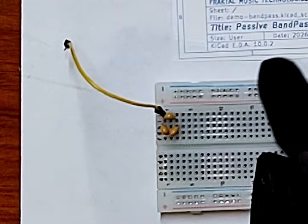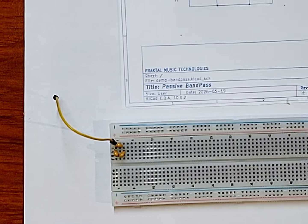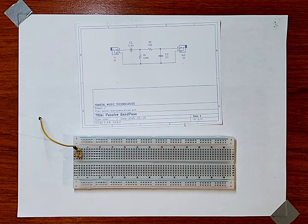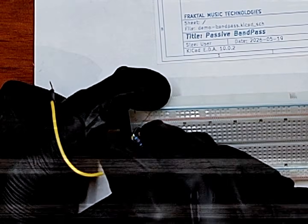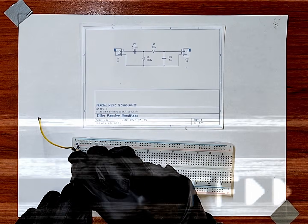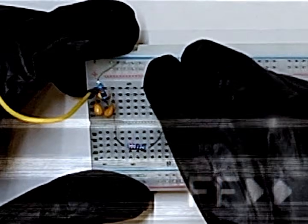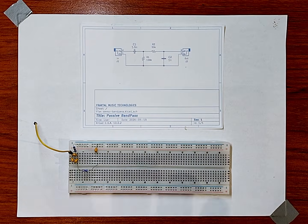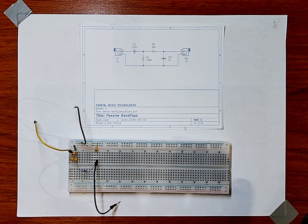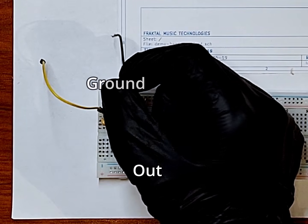Okay, so here we have our 1.5 nanofarad cap connected to our input, which is this yellow jumper right here. From here I'll connect a 100k resistor to ground like so. And now my second resistor from the same terminal. Cool, from here now I just have to connect my last cap to ground. Now I'll just connect some jumpers. And the circuit is done. Here, my blue jumper is my output, and the black one is my ground.